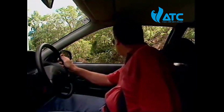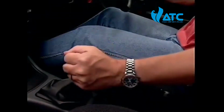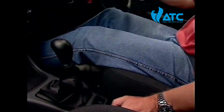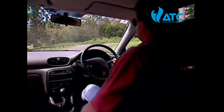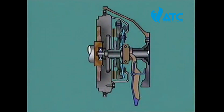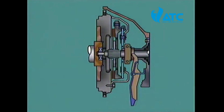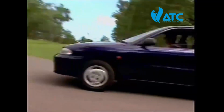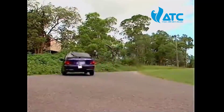This control is necessary when placing the transmission into gear. The transmission input shaft must be disconnected from the engine. When moving the vehicle from rest, slowly releasing the pedal gives a gradual engagement of the drive as the friction facings slip and allow torque to be applied progressively until both units are rigidly connected.